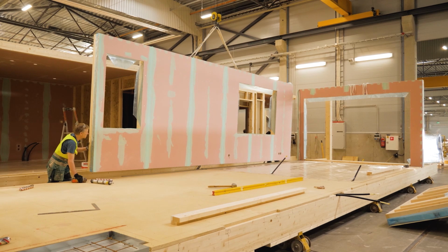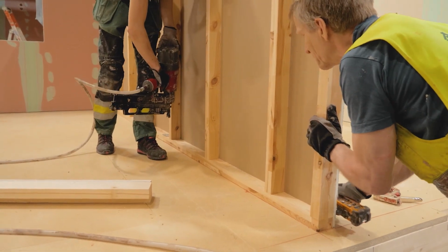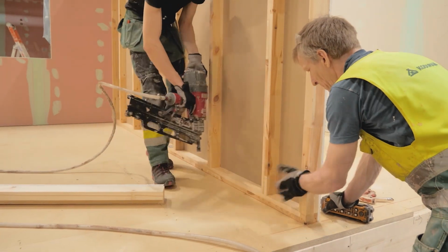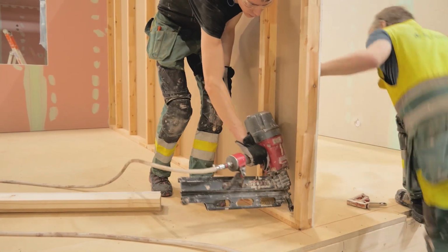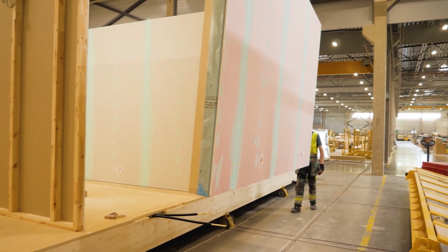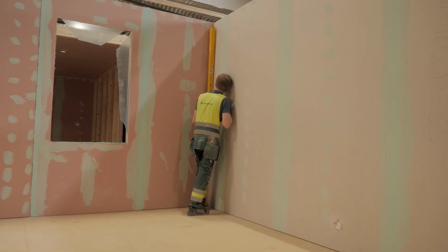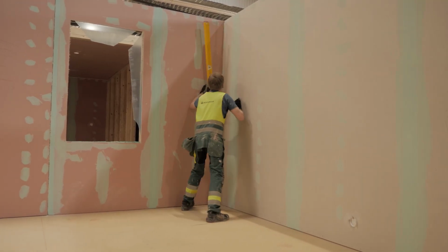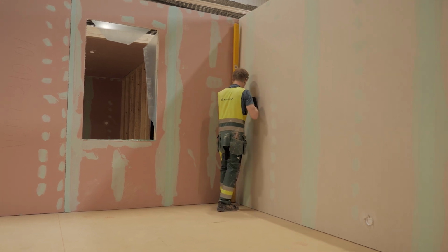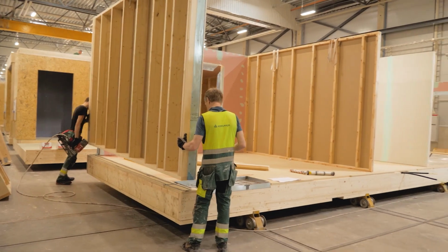If the longer side of the wall element is attached first, followed by the shorter end to form a corner, it provides better stability for the erected wall elements. However, depending on the developed solutions, the installation order may also be different. The vertical level of the wall elements must be regularly checked in the process of their installation. To fix the position of the elements, additional supports are used.